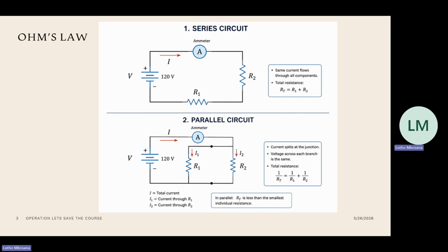So what makes them parallel is that when the current, which is current IT, is flowing into this node, it will thus split into two ways. Then I total is measured by I1 plus I2, and the resistors are connected such that the beginning of this resistor and the beginning of this resistor are joined into one connection. And then the end of those resistors are also connected at one point as well.